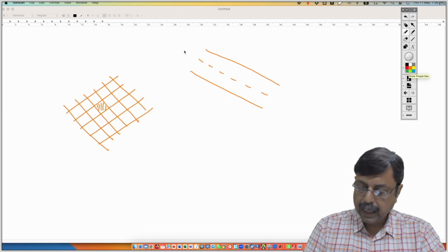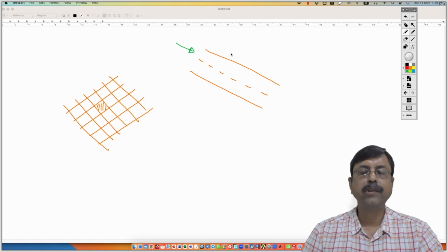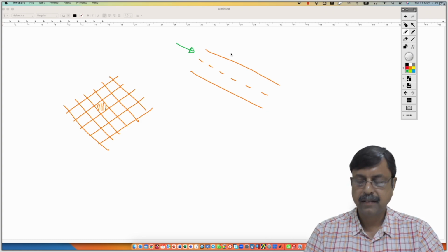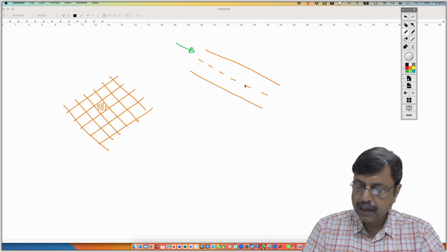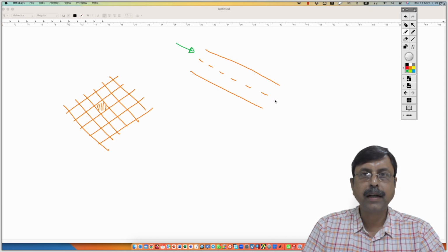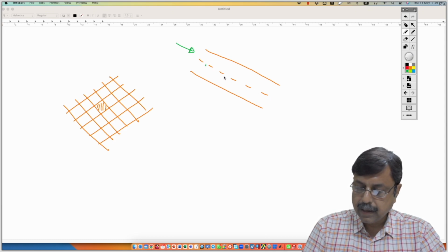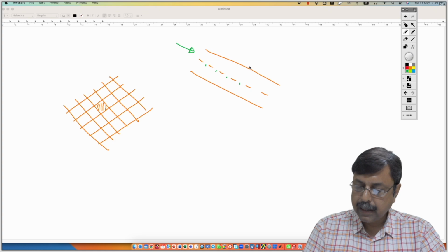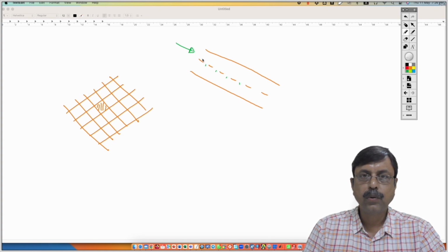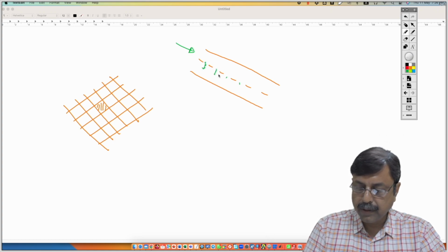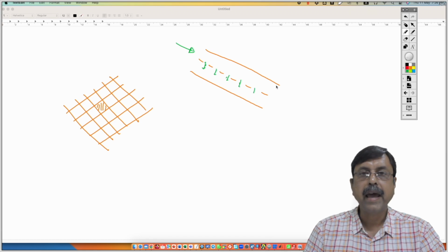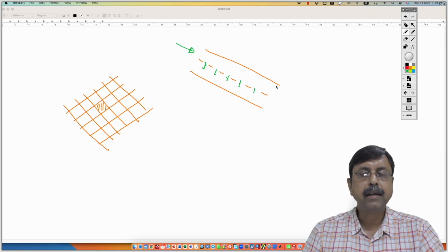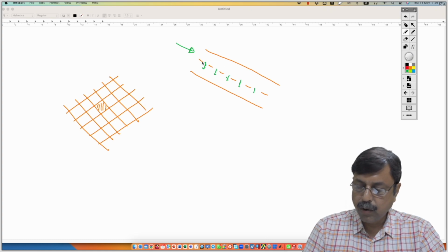So if feed, which consists of particles of different sizes, flows over this mesh, and the mesh is represented by this dotted line, and these are the perforations, that is the mesh. Then some of the particles which have size less than the mesh size will pass through these perforations, and the particles which have higher size will roll over and exit from the other end.